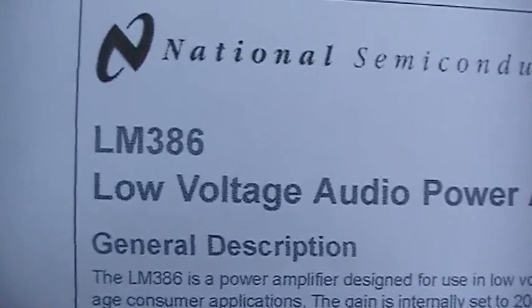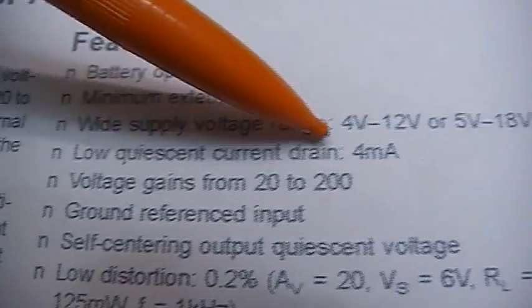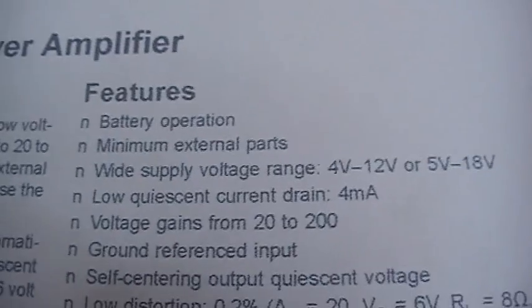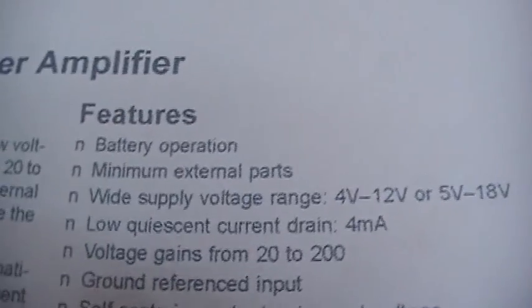But looking back into my data sheet of the LM386, we find here low current drain, so 4 milliamp only. So that is really an amplifier for battery operation.